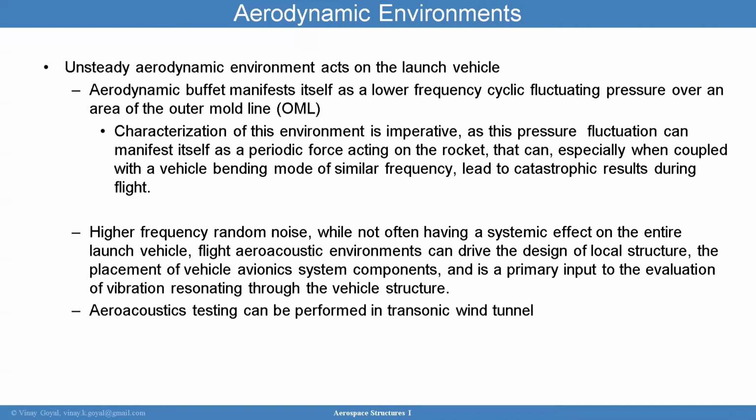You could also have higher frequency random noise, and it may not be on the entire vehicle, but you're going to have them. Flight aeroacoustic environments can drive the design locally, and it could maybe even make you think about putting the avionics system at different locations to avoid any interaction between this high frequency noise and the avionics. And aeroacoustic loading testing can be performed in transonic wind tunnel testing. Very important to understand that you can look at that in the wind tunnel testing, understand those environments a little bit better.